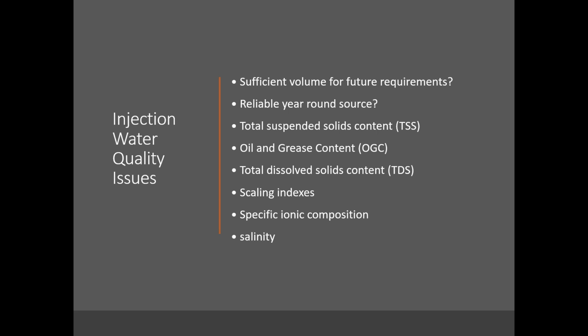There are some quality checks that are required on injection water. If you can see, there are different contents which need to be measured, and they should not be beyond a permissible limit in any of the injection waters. The first thing known to most of us is total dissolved solids. The total dissolved solids should not be greater than a particular amount in the injection water.